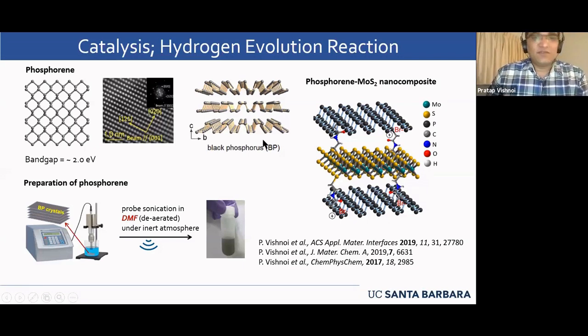And again, we make phosphorene out of bulk, an allotrope of phosphorus called black phosphorus. So you peel it. Phosphorene you can peel in two ways, which I showed with graphene. The other way is much more efficient, and I like this more because you can produce more amount in that. With the sellotape, you cannot produce a huge amount because, of course, it's high quality, but it will be only a few layers, a very little amount of material.